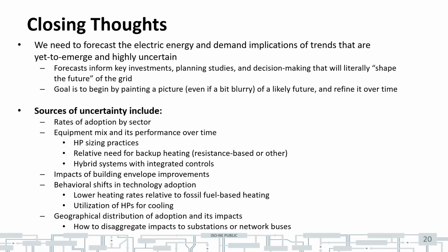I think one of the things that's really interesting is the behavioral shifts, right? I think what Ryan said is, you just can't deliver as many BTUs when it's really cold from a heat pump, right? The volumetric flow in the air of BTUs from a heat pump is different. It's less when it gets cold.